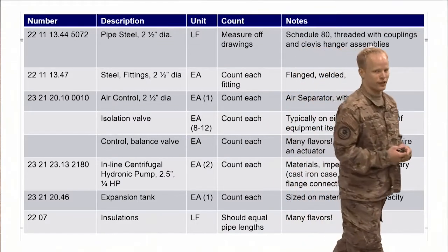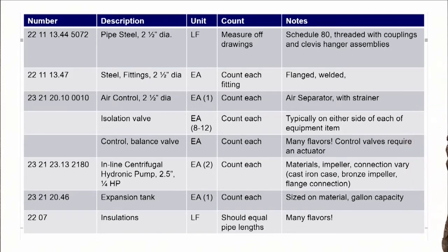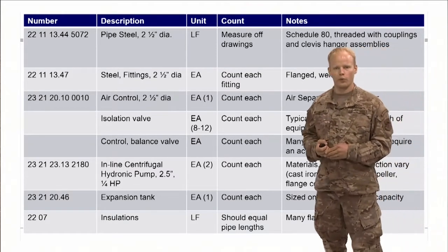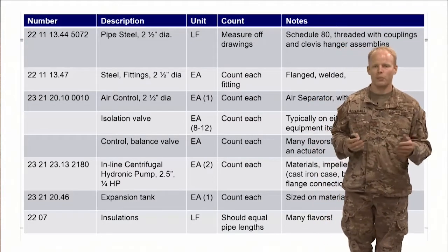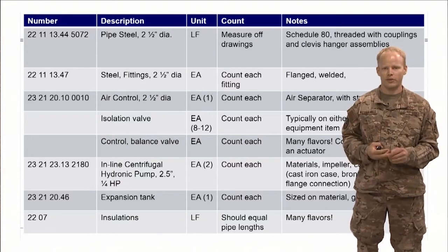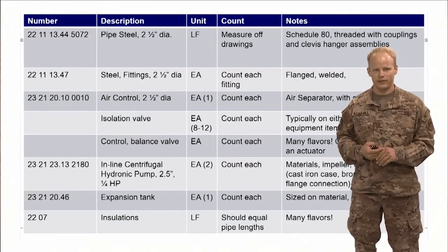And they have considerations. They can be flanged, they can be welded, they can be threaded, you name it. So go through and make sure you've read each of these. So your flanged will probably be easier for maintenance. Your welded, or easier from a labor cost perspective. Welded will probably be a little bit more expensive.